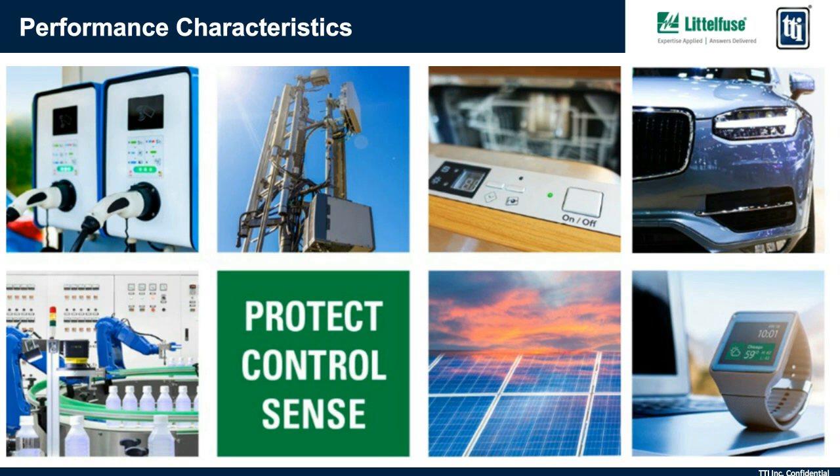Thank you, Brandon. So let's start off with talking a little more detail about high-speed fuse characteristics. High-speed fuses typically have additional published data and highly detailed data sheets when compared to general-purpose industrial fuses. Their data sheets include many characteristic curves that represent a fuse's electrical performance capability and show how 2 electrical parameters may correlate.